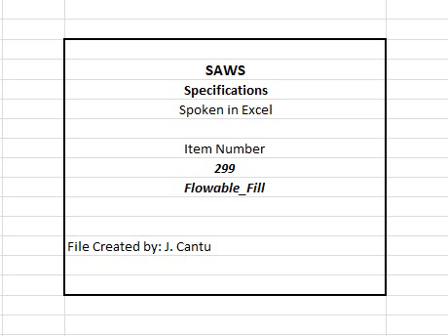2. Two specimens are required for a strength test, and the compressive strength is defined as the average of the breaking strength of the 2 cylinders. 3. Contractor to transport, strip, and cure the test specimens as scheduled at the designated location. 4. Cure test specimens in accordance with TXDOT Standard Laboratory Test Procedure Tex 447A.